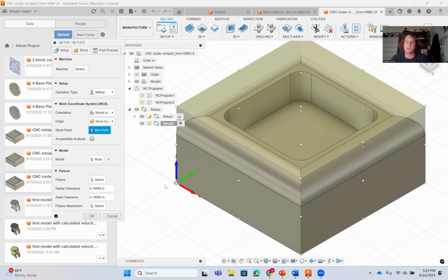You could use it with aluminum, and I use it pretty often with wood or MDF. There are better ones for wood, but it works really good with MDF. It works really good with plastic. It works really good with aluminum, especially if you don't have the ability to use coolant. So for that reason, you could set a tool offset height and keep that for as many jobs as that tool lasts, which is really helpful. So that's why you put the coordinate system on the bottom.